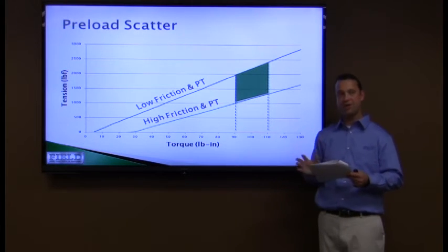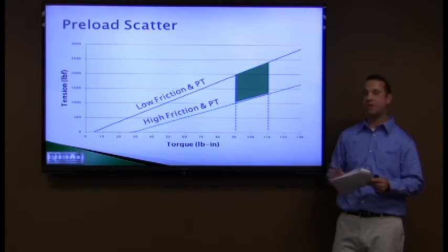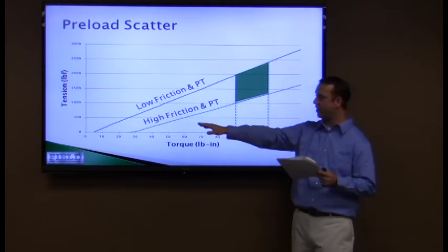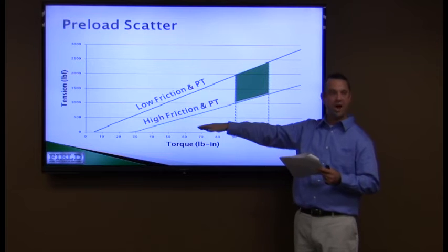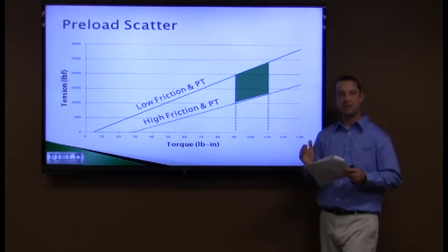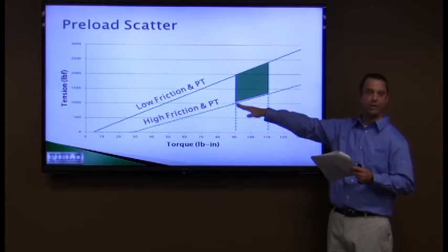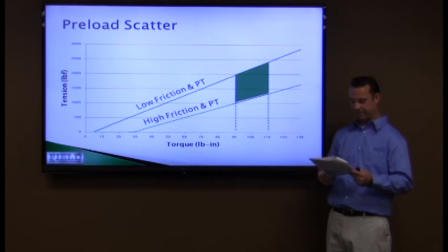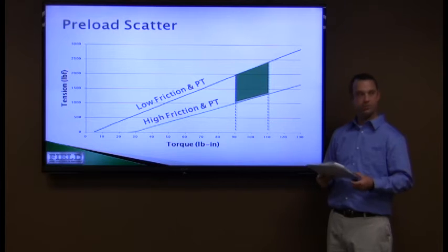The best joint is generally the simplest joint because it's the easiest to control. When you start adding things like lock nuts or lock washers that aren't always necessary, in some cases you may just be adding more variables to your joint, which is going to increase your variation.